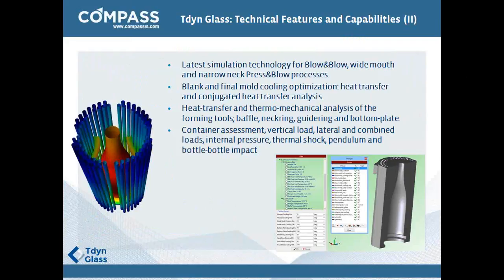Tdyn Glass incorporates the latest technology for simulating blow-and-blow or press-and-blow processes, and also blank and final mold cooling optimization can be performed, together with thermomechanical analysis of forming tools such as baffle, neck ring, or bottom plate. Regarding container assessment, a wide range of different standard load tests can be simulated, as we will see later.